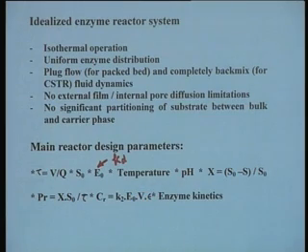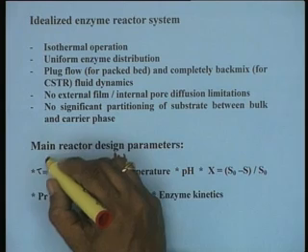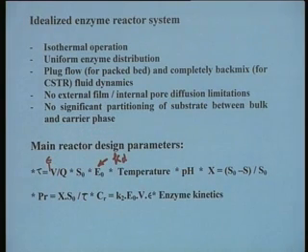Of course here, even in the case of tau, we can multiply it by the void age if you want to consider a broader picture of a packed bed reactor, because this V, the reactor volume, is not the packed bed volume, it is the volume of the fluid in the reactor. So obviously the total bed multiplied by the void age will give you the fluid volume in the reactor. In the case of a CSTR, void age can be considered almost equal to 1, because the volume occupied by the carrier is very small compared to the total reactor volume.